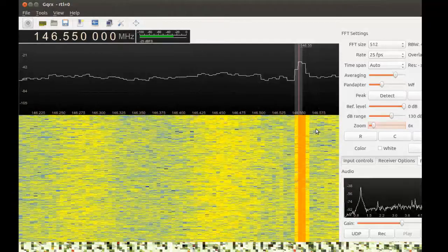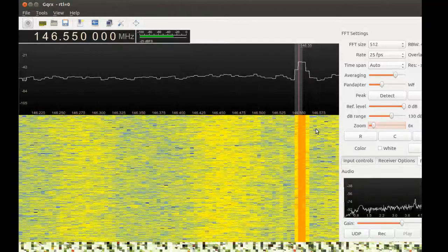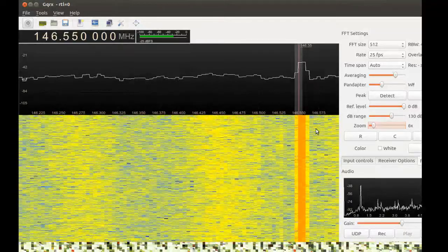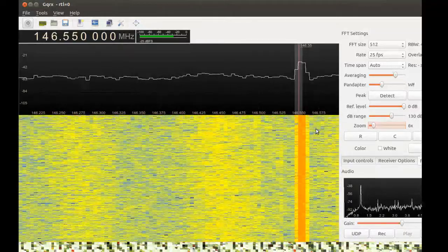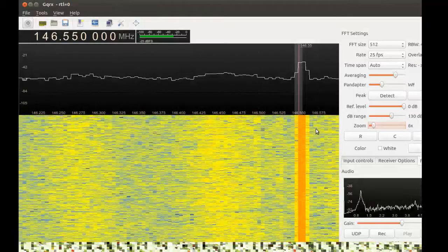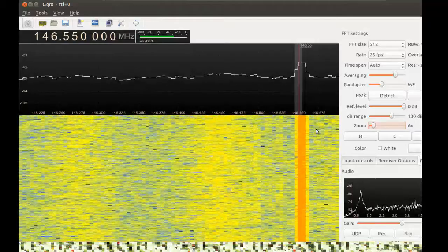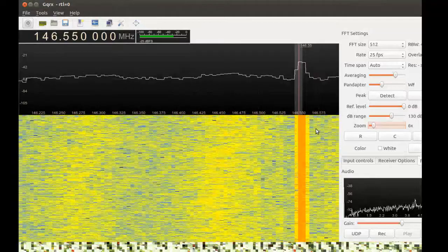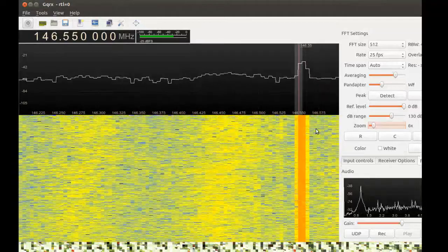So is that just because of processing speed and stuff? Yep. The processor can't handle it. So your FFT calculation takes up a lot of CPU. The higher you have that number, the more time it spends doing that calculation. And then it takes a bit of CPU to pass the audio from one program to another, and then FLDigi has its own CPU usage. Everything's taking a trip off. Yep.